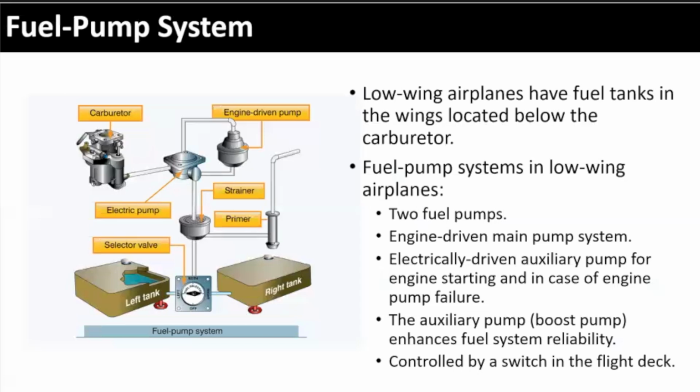Okay. Typically, these aircraft are going to have a fuel system that has two pumps. Why do we have two? Redundancy, right? Exactly. If something happens to that engine-driven fuel pump, from the time you hit the magnetos and crank on the engine, that engine-driven fuel pump is what's driving that fuel flow. If something happens to that engine-driven pump, hopefully it's not the engine going bad, you've got an electric auxiliary fuel pump to turn on and also facilitate pumping of that fuel into the engine.